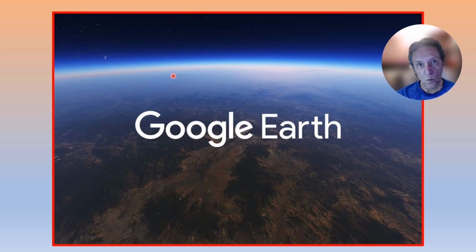One of the first things you want to do is go to Google Earth and look at that property and see if you can get some feel for what type of ground it's on, what the features look like from up above, where existing structures are, all sorts of things. You can get quite a bit of information, perhaps steepness of slope and other information that are valuable to help you plan your investigation.